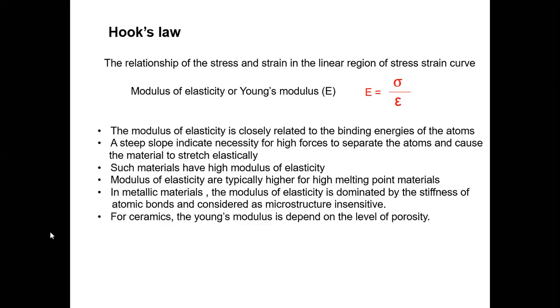But for materials like ceramics, the Young's modulus is dependent on the amount of porosity. That means how many pores are there, right? If less porous, this can change like that, right? So this is some information about the Young's modulus and the characteristics of Young's modulus in a few materials, right?